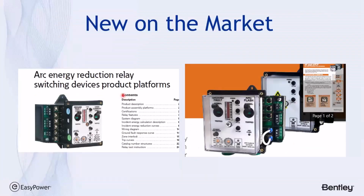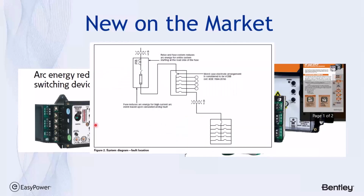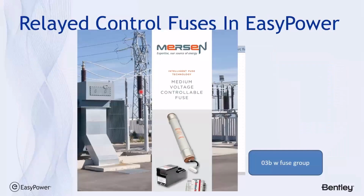Now, some of the equipment that looks like this is available now and has data sheets on the market, and they can incorporate, in a one-unit system, the ability to detect ground fault, short circuit overcurrent, and maintenance, including maintenance mode. And so in EasyPower, they'd be simulated something like this.